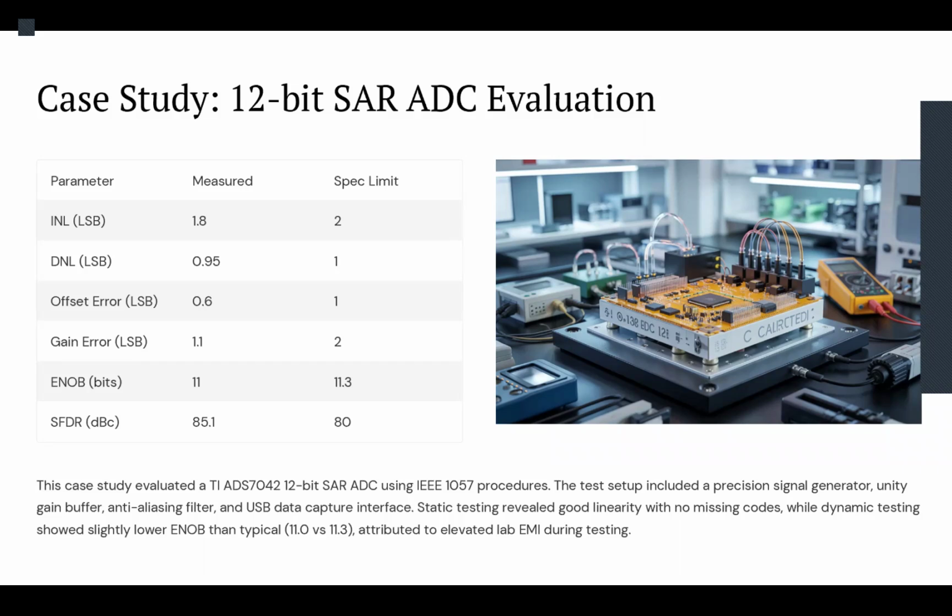When we run this test on the specific ADC, we measure different static parameters like INL. In this case, the INL measured is 1.8 LSB, which is within the specified limit of 2 LSB, so this ADC passed this parameter. The DNL measured is 0.95 LSB, which is also under the limit.